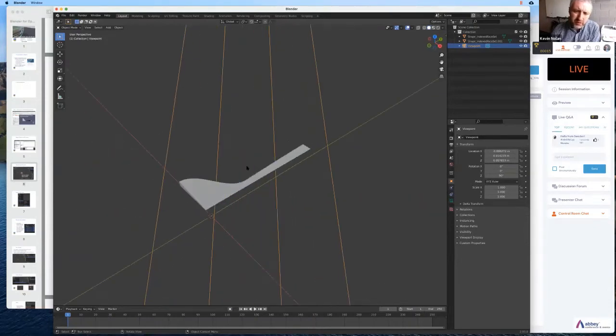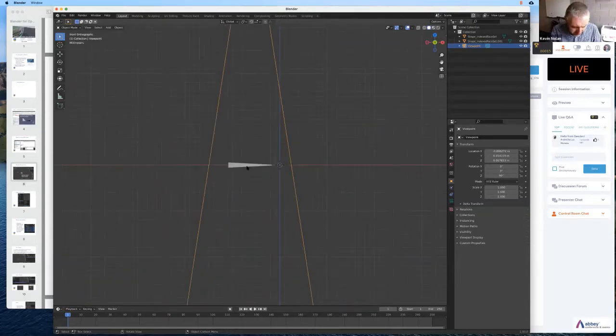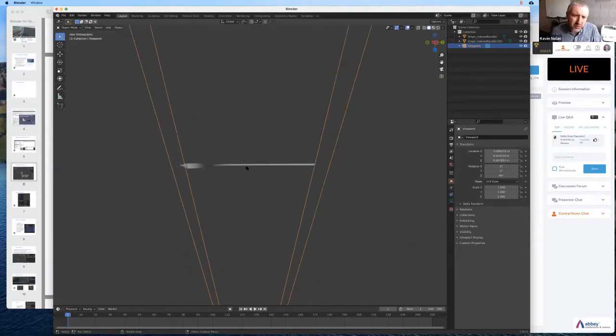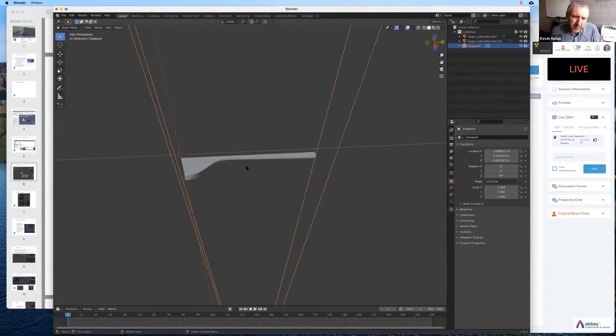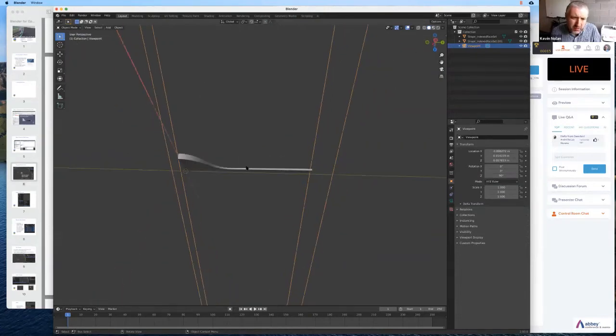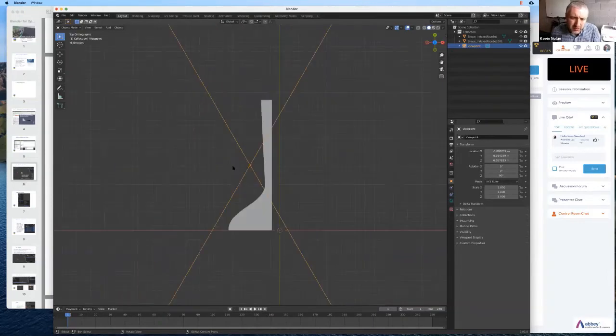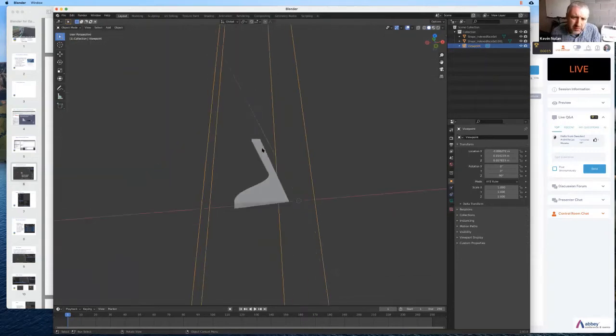By default, Blender makes a lot of very clever use of a numerical numpad. It uses 1, 3, and 7 to orientate your X, Y, and Z position. So 7 is the top view. And then 5 is used for perspective and orthogonal. And then you can use 4, 6, 8, and 2 to move it around.